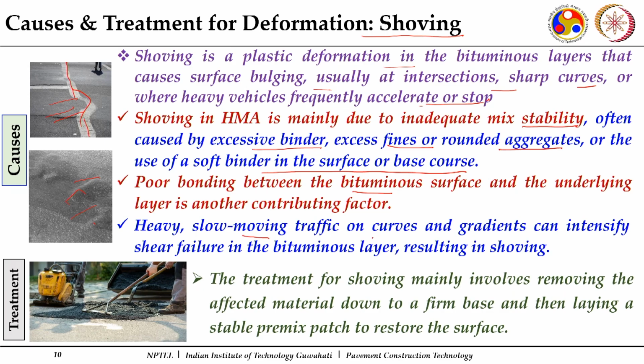Heavy slow moving traffic, especially on curves and gradients, leads to these kinds of failures in the bituminous mixes. That is why on horizontal curves or at gradients, where frequent stops or accelerations are made, we can experience these kinds of distresses in the form of shoving.